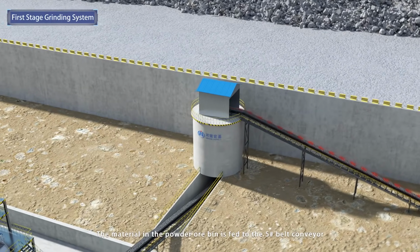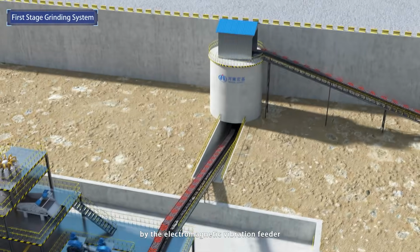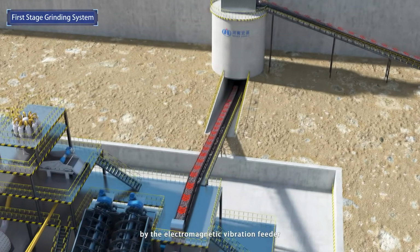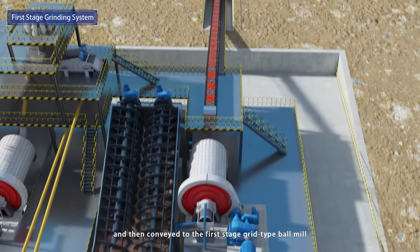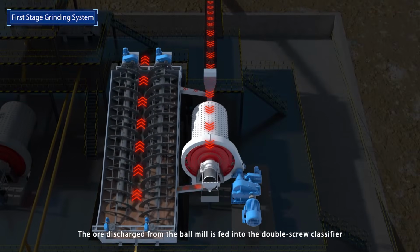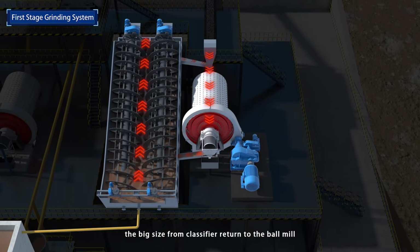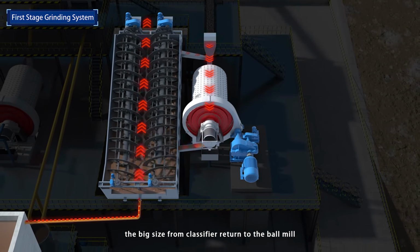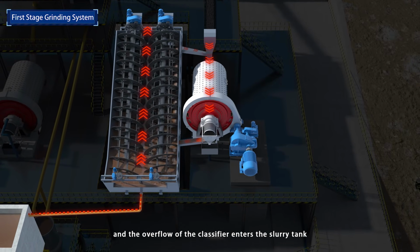The material in the powder ore bin is fed to the five-belt conveyor by the electromagnetic vibration feeder and then conveyed to the first stage grid-type ball mill. The ore discharged from the ball mill is fed into the double-screw classifier. The big size from the classifier returns to the ball mill, and the overflow of the classifier enters the slurry tank.